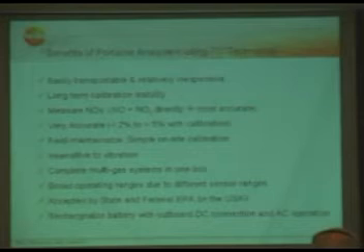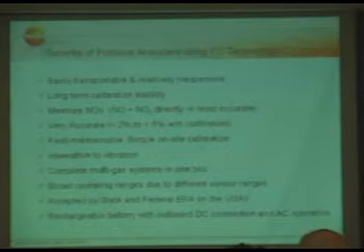This is in some applications a big advantage, or if you have a gas engine running in the desert somewhere where no power is available, you can also connect from the starter battery of this gas engine, or if there is a battery available, you can just put 2 wires to our analyzer and provide those 12 or 24 volts to operate in the field.